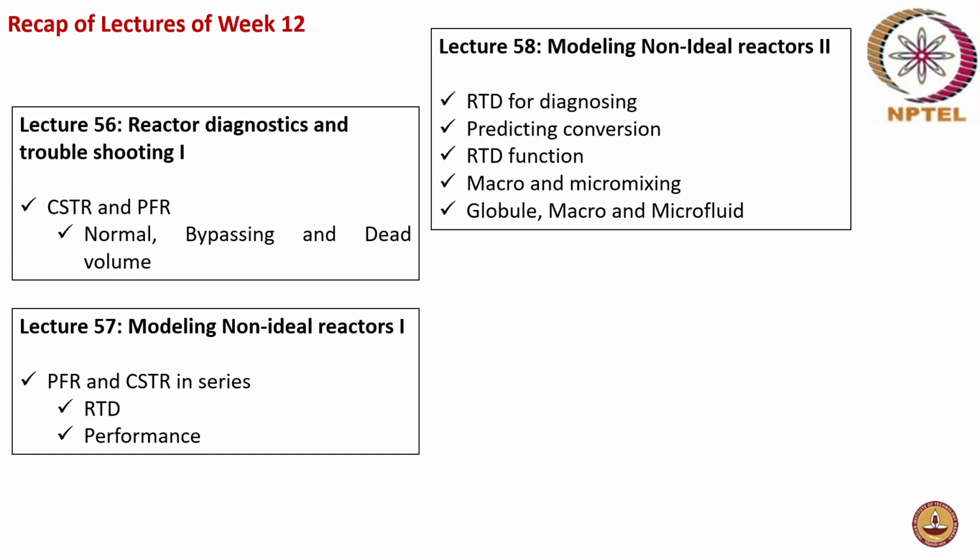This was followed by a discussion on macro and micro mixing, where in macro mixing there is no mixing at the molecular scale. However, in case of micro mixing, the molecules have microscale, molecular level interactions and mixing between the different molecules. And then certain definitions like globule, macrofluid and microfluid were all discussed.